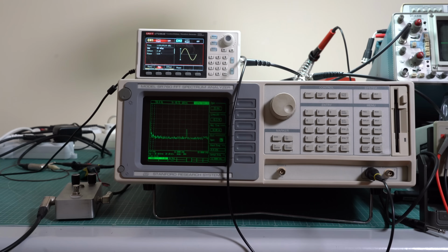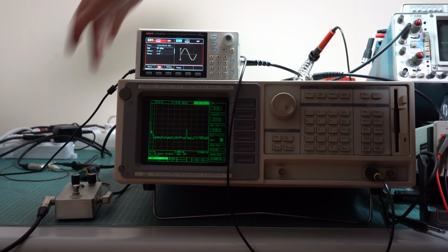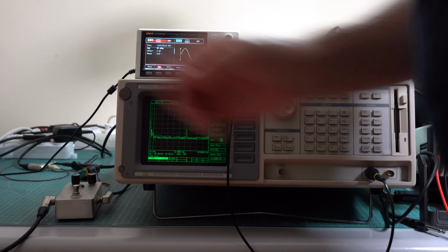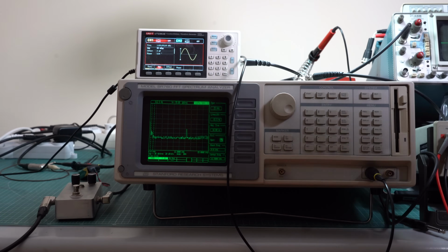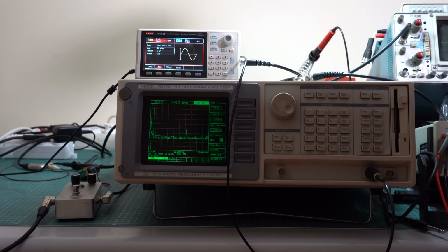And finally, the spectrum analyzer is really useful for characterizing distortion and measuring the THD. So if you want to ruin the day of your favorite friend who's an audiophile obsessed with vacuum tubes, just measure the THD of their amplifier. In order to demonstrate this, I decided to set up an experiment that consists of a signal generator, a guitar amplifier and a guitar pedal, which is actually a fuzz pedal. Now the fuzz pedal is supposed to add distortion on purpose in order to change the tone of the instrument, so it's a really useful tool for seeing how the spectrum changes when we add distortion.